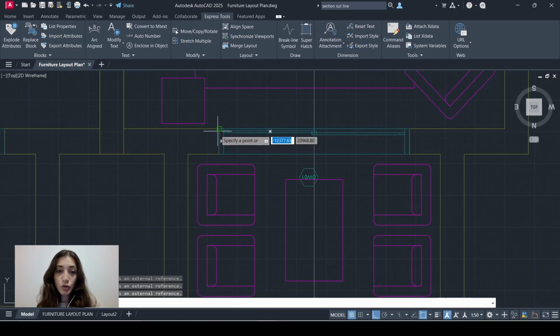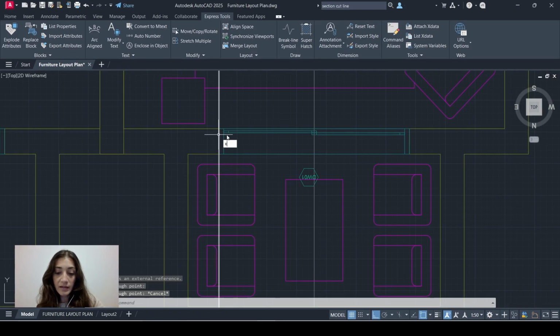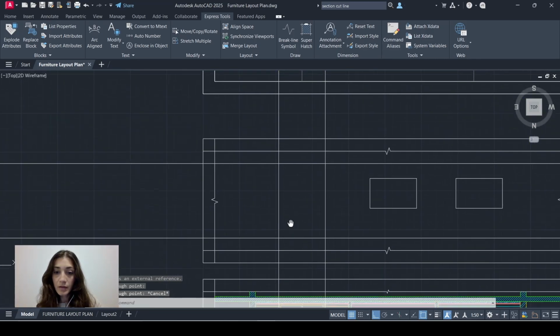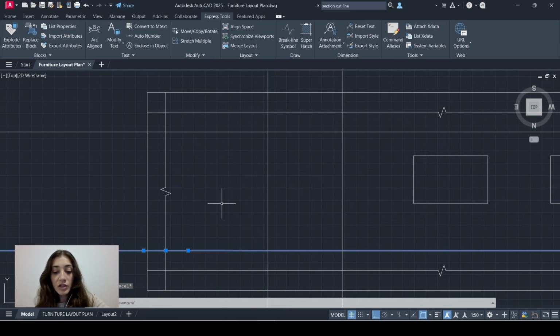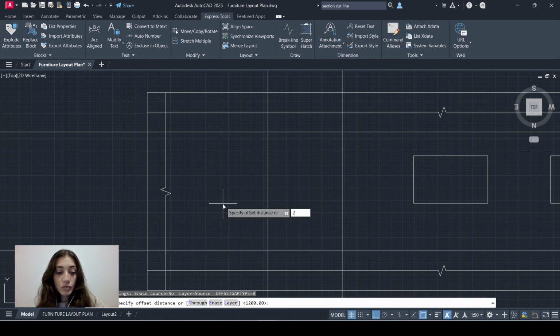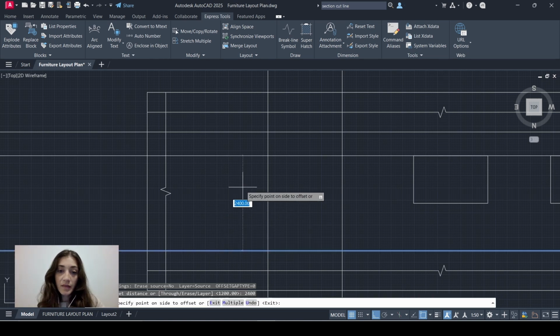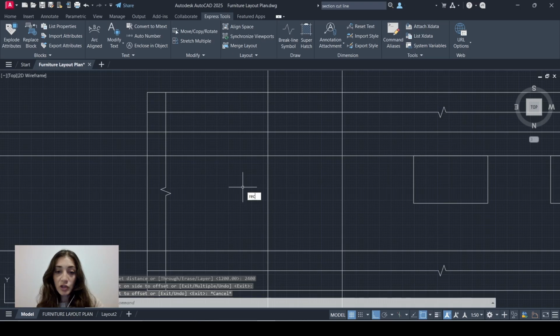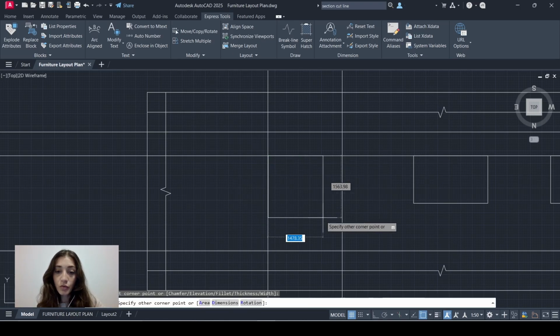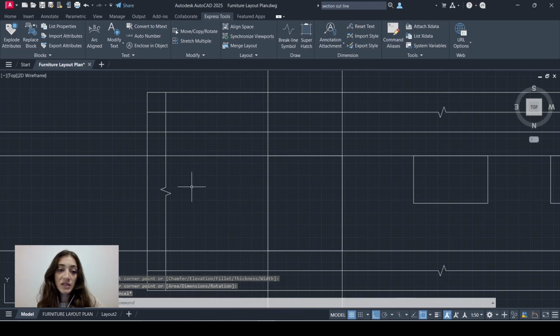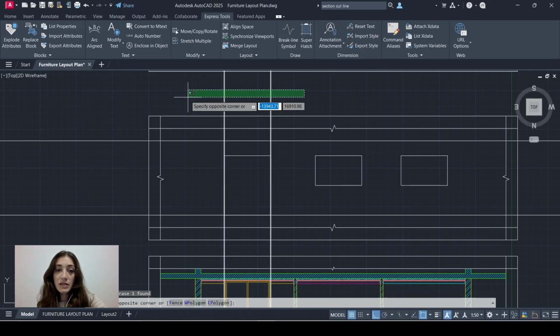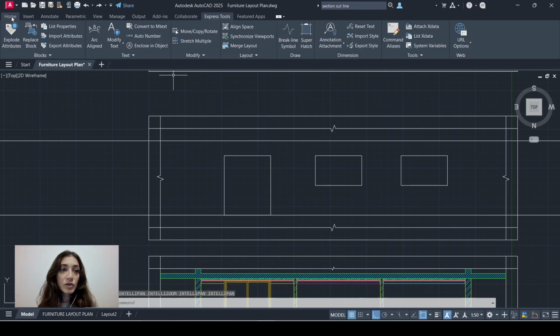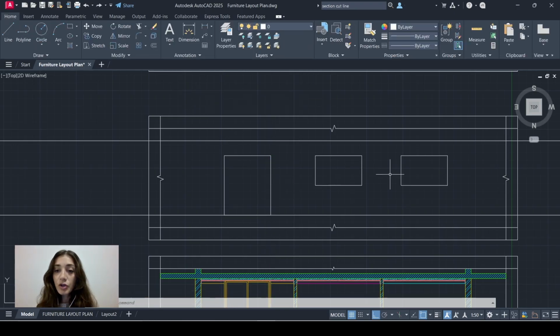Here I have a door window because it's leading to a balcony. I'll just select the floor finish level and offset it by 2400, which is the height of the door window, and I'll draw a rectangle over this newly defined space. Now I can remove this and those. And now I'll just go back to my home tab and I'll start drawing the windows.